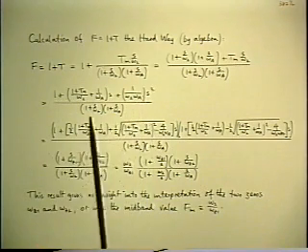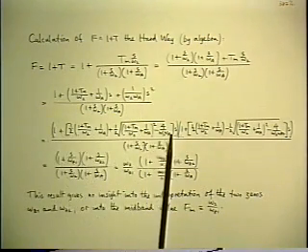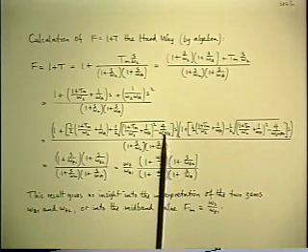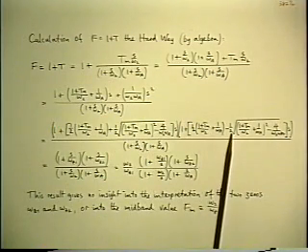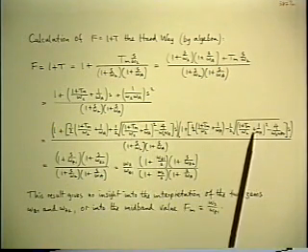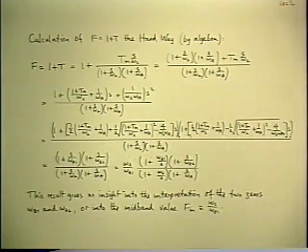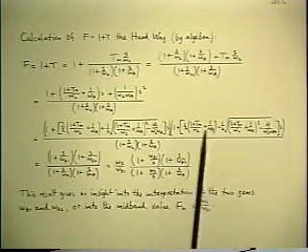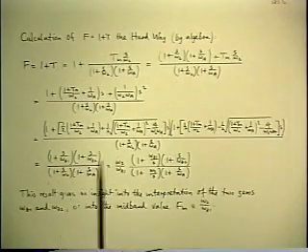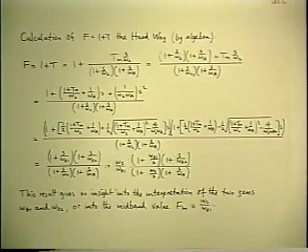And then if you resort to the conventional formula for the solution of the quadratic, this is what you have to substitute for the two roots in order to write the two factors of the numerator, to find the two zeros. And you see what a ghastly mess that is. You have this whole long expression in the square bracket representing the new corner frequency that we found so easily.